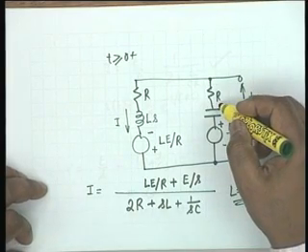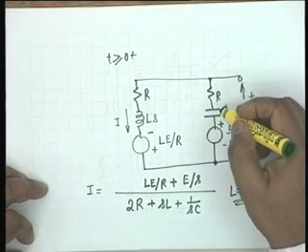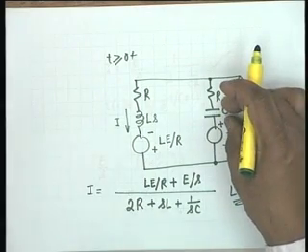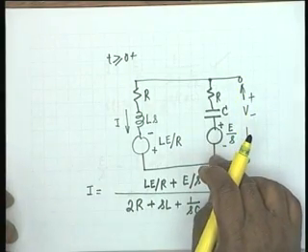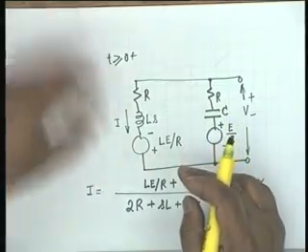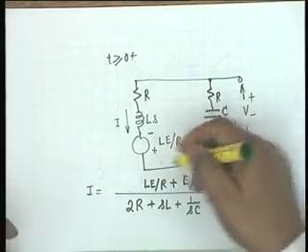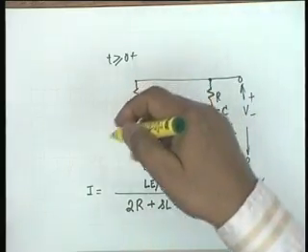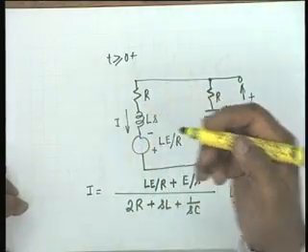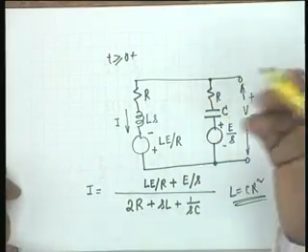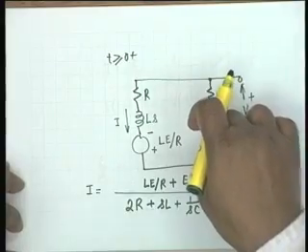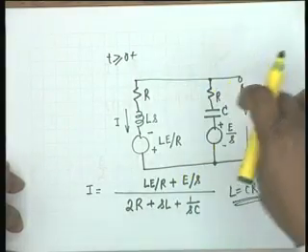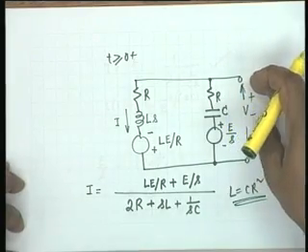No, the capacitor is fully charged. Resistor, because of resistor, fully charged at t equal to 0 minus. The voltage across the capacitor is equal to E, and therefore there cannot flow any current through this resistor. Okay, and then as soon as the battery is disconnected, current has to flow. So it flows in the capacitor in the opposite direction to discharge the capacitor, and ultimately after an infinite amount of time, there is no current. And even though a current flows in the loop, the element values conspire to make this voltage drop across the combination equal to 0.